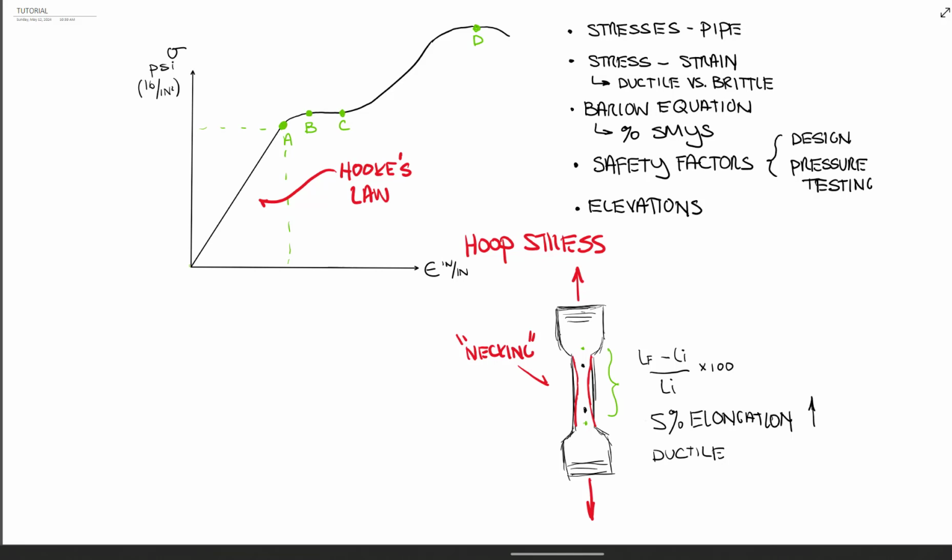Hooke's law is basically the behavior of a spring, and that's usually represented by F equals negative kx. F is the force, k is the spring constant, essentially how stiff the material is, and x is the displacement, or how much you've stretched something. So overall, the main takeaway is anything in here, the materials will act as a spring. If I pull on something, like a spring, and I don't pass point A or B, and I let go, that material will go right back to the way it was. That's what we want.